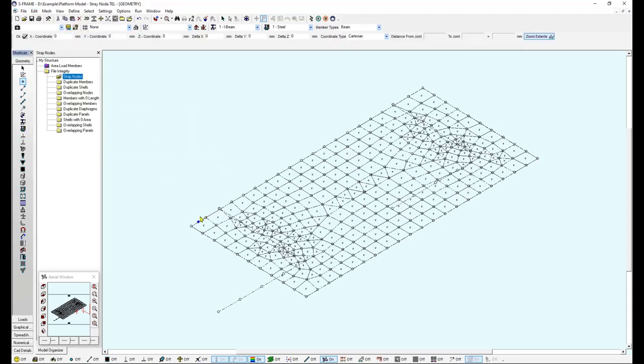So if I select the Join tool, with Control, I just click and drag over that node and it will be deleted. If you're not sure about how these nodes appear in the first place, it could be due to some modeling, or the most common case we have seen from clients is when they import from a third-party product, such as a DXF file from AutoCAD, ETABS, STAAD, Revit, etc. It's always recommendable to check your integrity checks before proceeding.